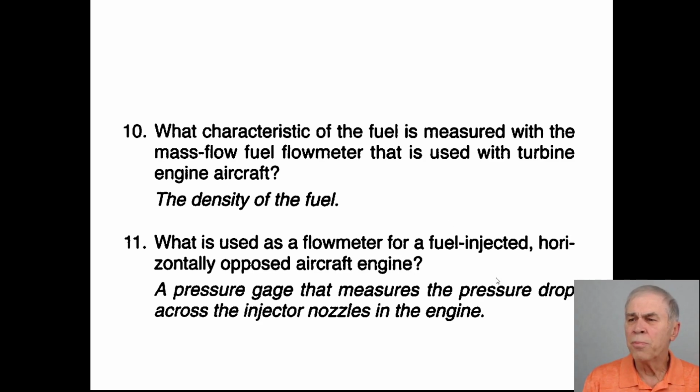And it measures the pressure drop across the injector nozzles in the engine. It's nice if you can go a little further and actually point to the precise point, the exact spot that is being measured. And if it's fuel injected, you're going to measure right at the injector nozzles. Because you want to see how much fuel you're injecting, at what rate or at what flow.